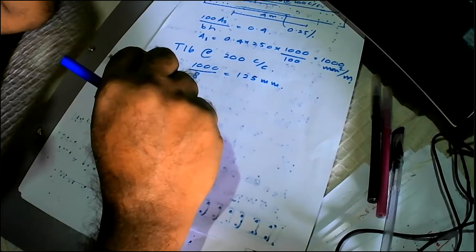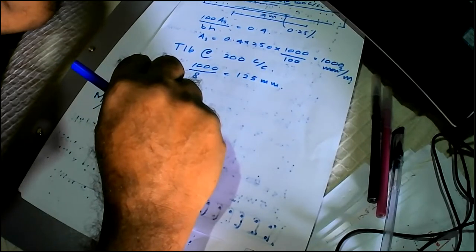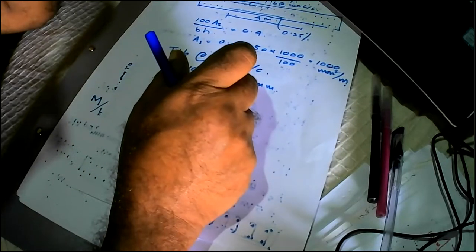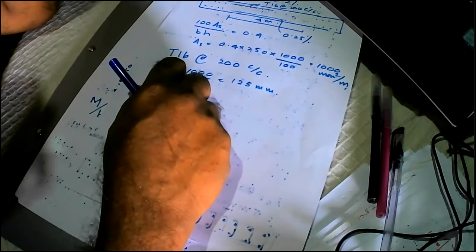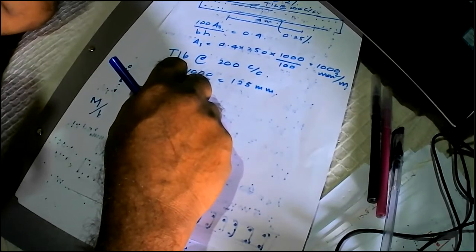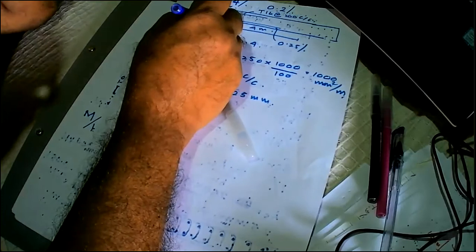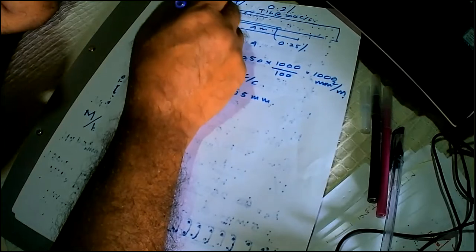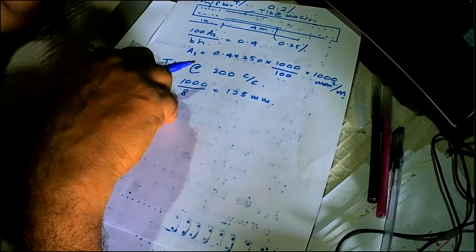Sir, while finding the t value, how did you subtract that 500 from 6,000? Yeah, actually, I considered that the end zone will be 1 meter. So the midpoint of the end zone is 500 millimeters from the end of the wall. When I say 1 meter, like a midpoint of the reinforcement? Yeah. Because all these reinforcement will have a centroid. So I have to consider this. I have considered the centroidal location of the reinforcement. Okay, sir. Understood, sir. Thank you, sir.